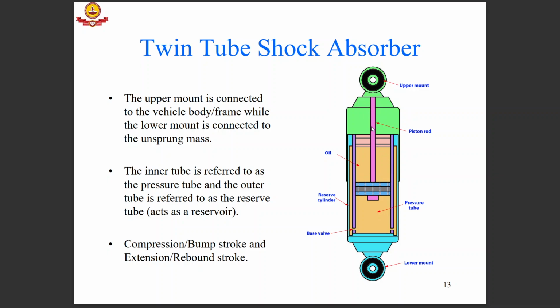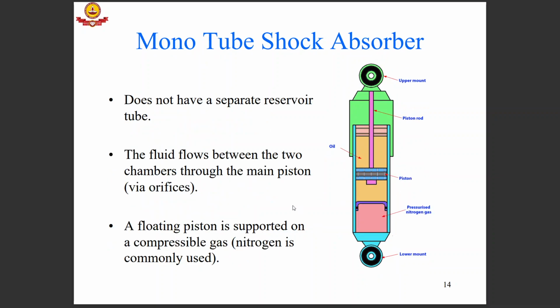Of course, if the velocity of motion of the piston rod increases, this force will be higher, and if it is low, it can easily move through the oil. And that is why we get the force equation for a damper as F equals C times x dot.